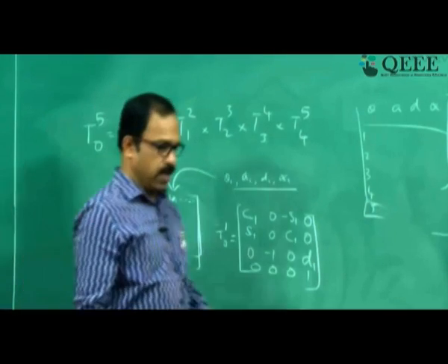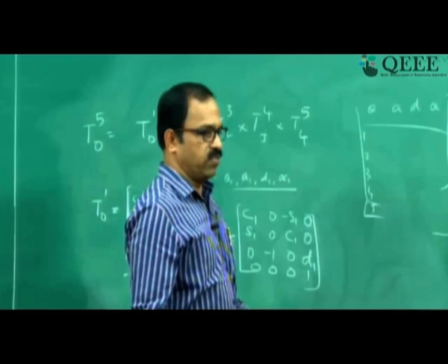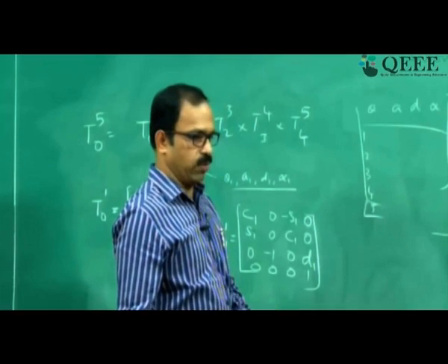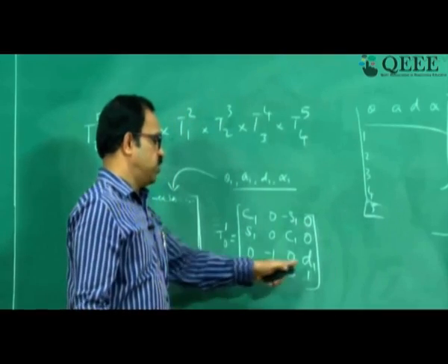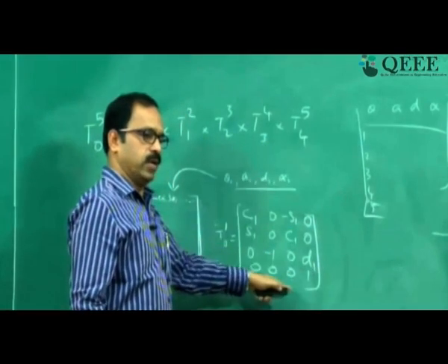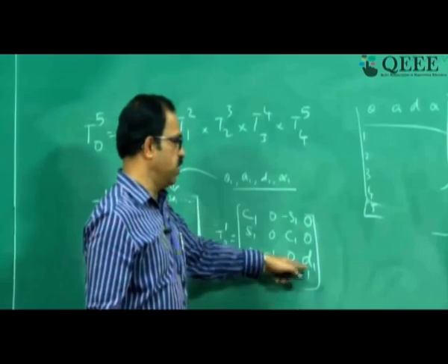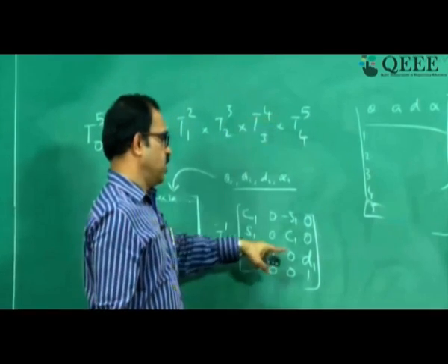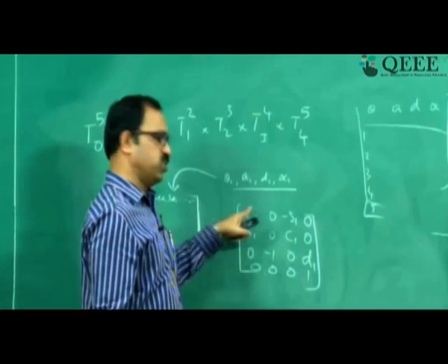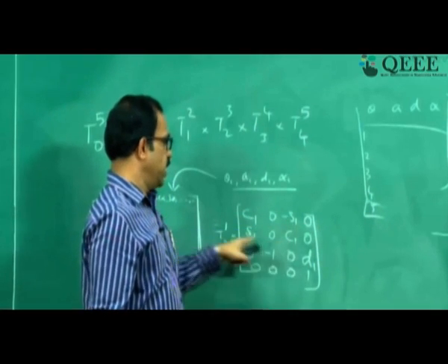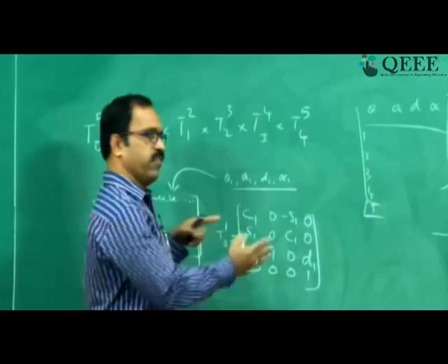Now if you look at the coordinate frames here, you can see the initial frame L0 with x0, y0, z0 and then x1, y1, z1. L1 is d1 away from the origin L0, and it has rotated by 90 degrees, and that's why you get this matrix here, with the minus 1 and this rotation. Depending on theta 1 it will have a different orientation.